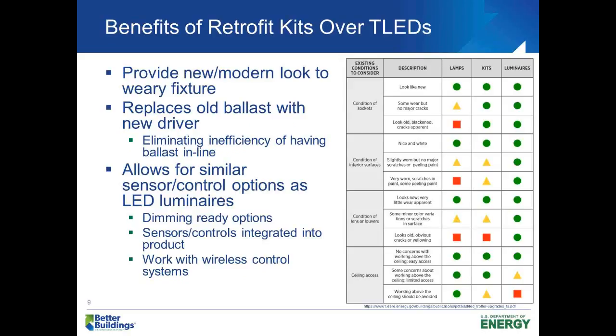So in summarizing the benefits of retrofit kits over plug-and-play TLEDs, they can provide for a refreshed look to a worn luminaire, provide new electronics, and enable various control options. Various tools exist to help determine whether TLEDs, retrofit kits, or luminaires may be the best choice depending on your criteria. On the right of this slide, you'll see an example from the Department of Energy, a report that considers the conditions of the sockets, interior surfaces, lens or louvers, and whether there are any restrictions in accessing the space above the ceiling. There are other similar graphs that can help you determine, depending on whether you want control or some other requirements of your particular project.